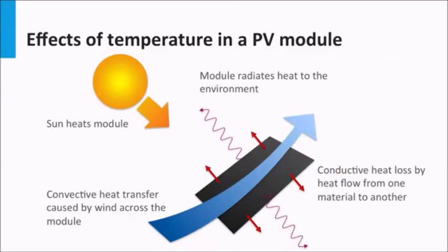There could be several factors impacting the heat flow in and out of modules. Encapsulation of the solar cells is a major factor in increasing the operating temperature of the PV module. The eventual operating temperature of a module will be a result of the thermal equilibrium between the heat generated by the PV module and the heat lost to the surrounding environment. The heat exchange with the environment in turn could depend on several factors like ambient temperature, wind, heat transfer coefficients between the module and the environment, and the thermal conductivity of the module's body.